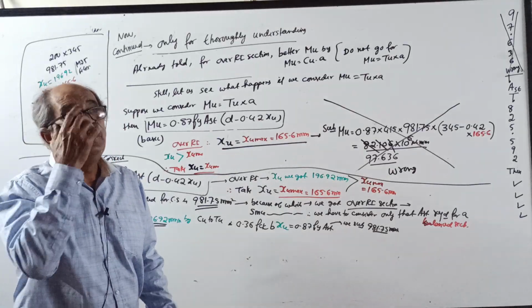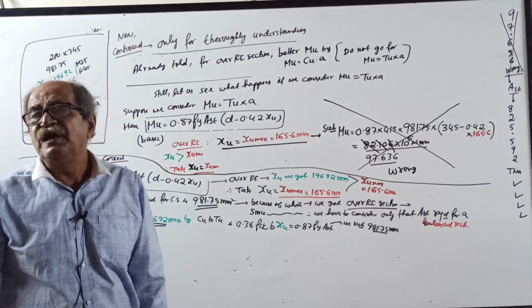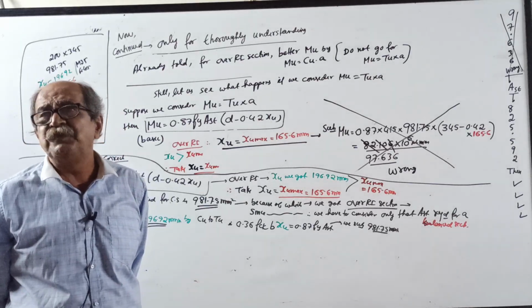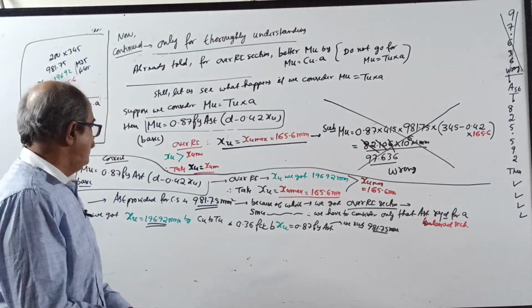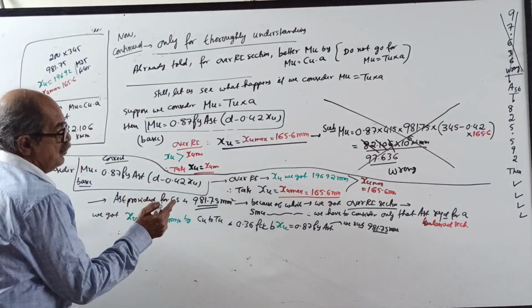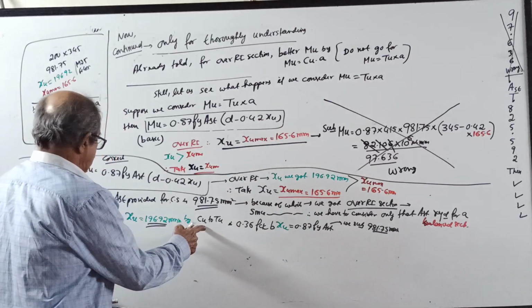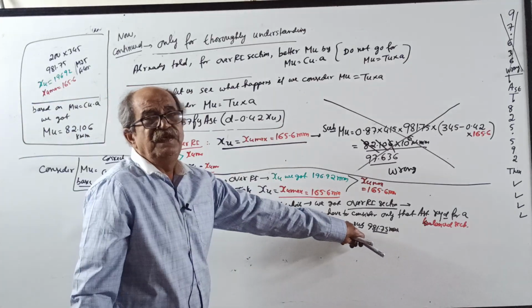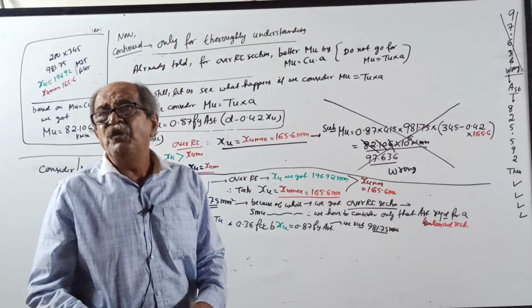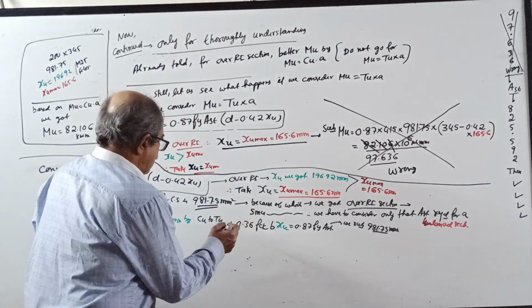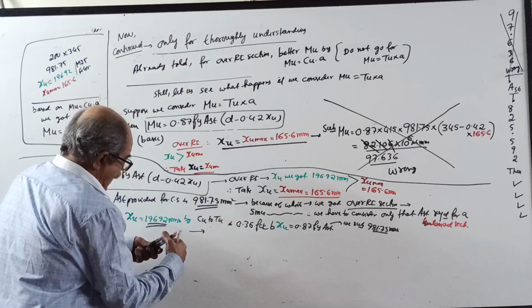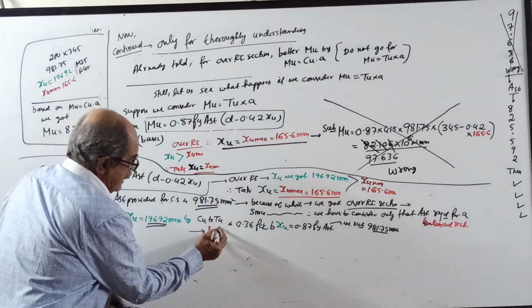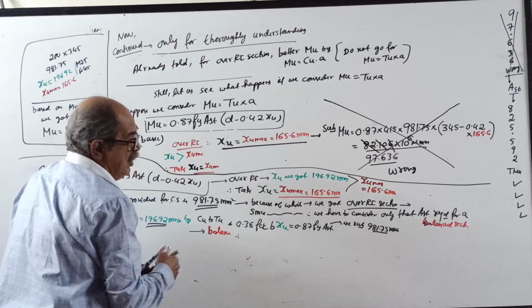See, definition. Over-reinforced section is one where area of tension steel provided is more than that required for a balanced section. Therefore, you got over-reinforced section, you write here. But this is the steel which gave over-reinforced section. But restriction, we have to find strength only corresponding to balanced section. You should write all the statement, balanced section. Therefore,